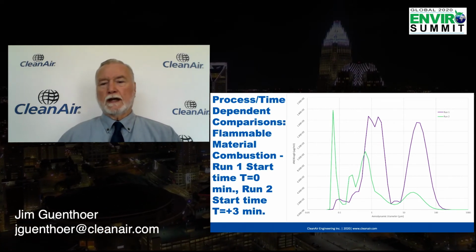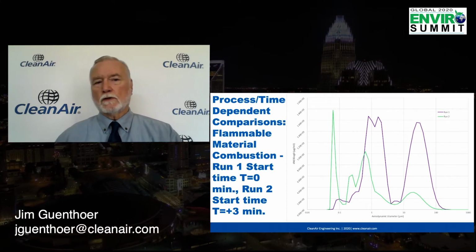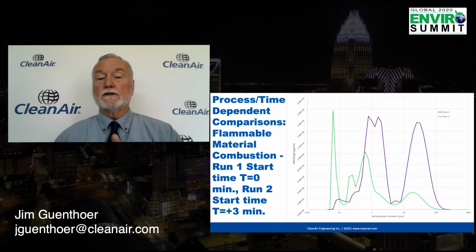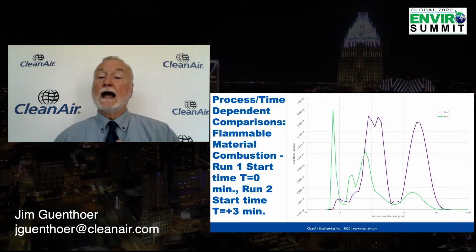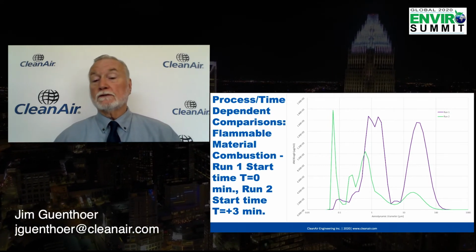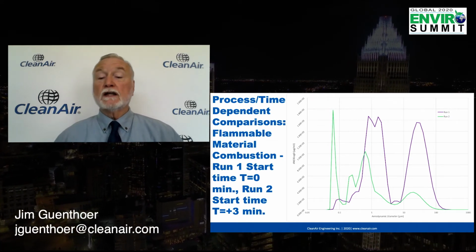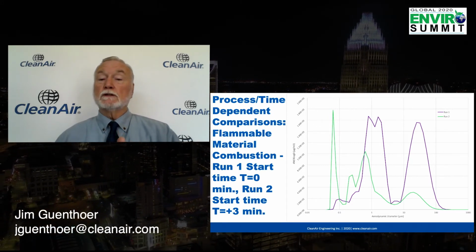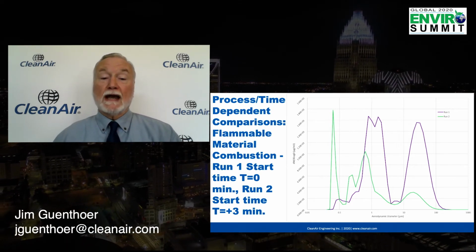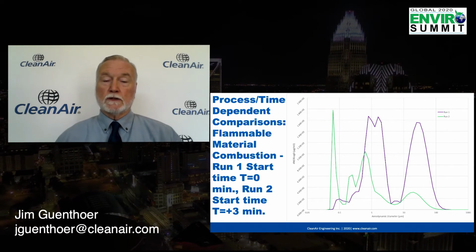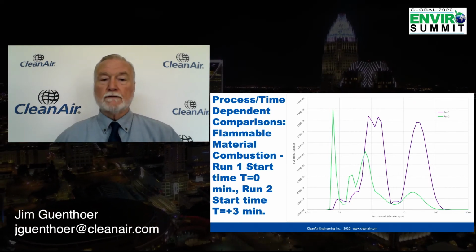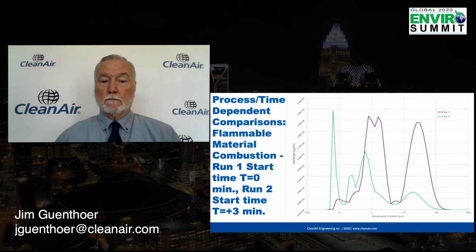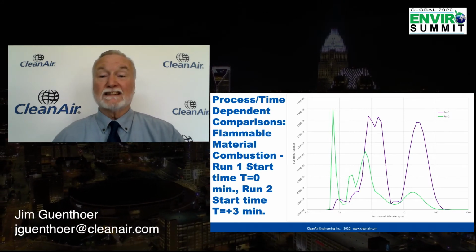After we did that sample, we said, okay, let's see how thorough this combustion is. So they did another burn in this trial facility. We waited 3 minutes, and then we started the process. You can see from the green trace how everything shifted down, as we talked about. Now we have a trimodal distribution where there's very little larger size char left. We have a good amount of combustible material in the middle, combustion products, but now we have vapor phase condensation. It's very hot in the chamber. We have gases that are being driven off, and as they reach downstream in the duct where we're sampling, they've condensed into submicron particles. As you can see, that has a size of less than 1/10 of a micron.